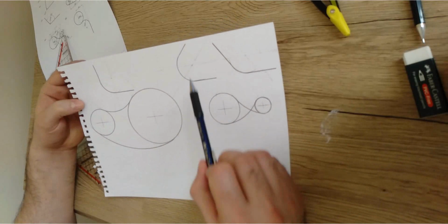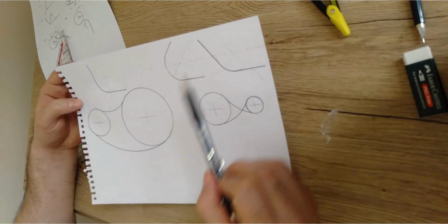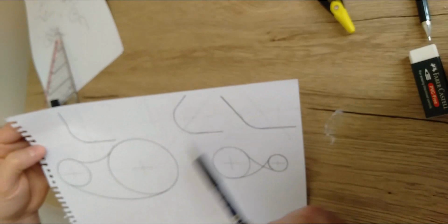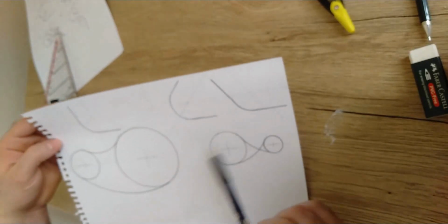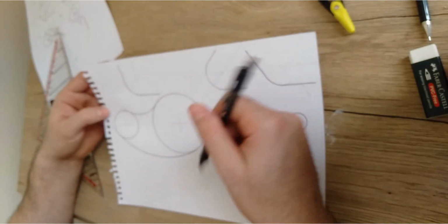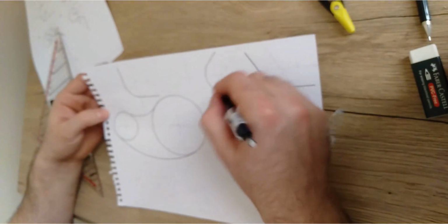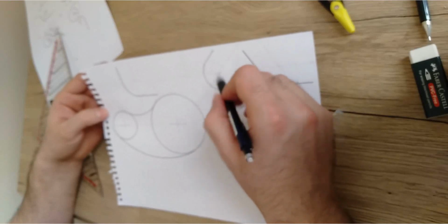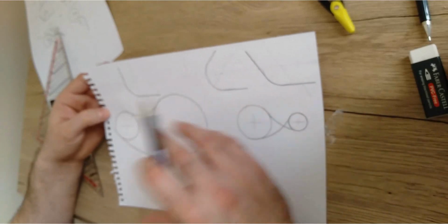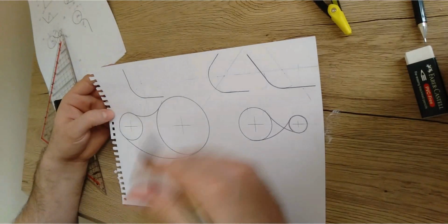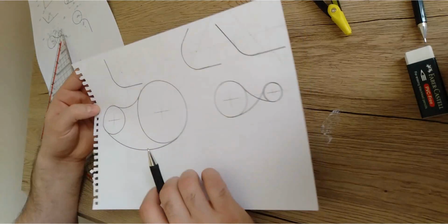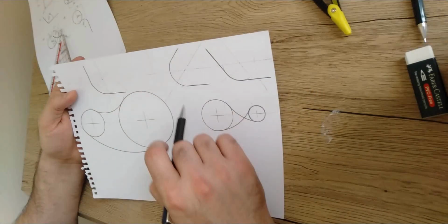But as you can see, these lines are already seen. You can see them in the video. But I pushed hard while I was drawing this line just so you can see them in the video itself. But while you're working, you shouldn't draw these lines to be clear. These extra lines are not existent in the drawing, so do your best to make them very light or barely seen, so you won't spend time erasing or removing them from the drawing. But it is fine even if you just leave them, but they should be very, very light.